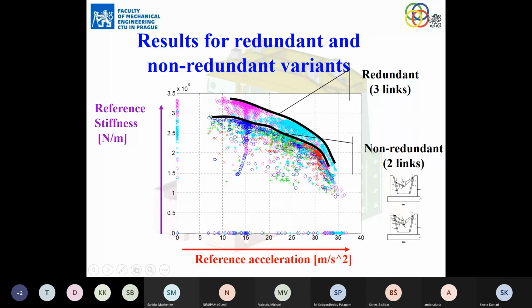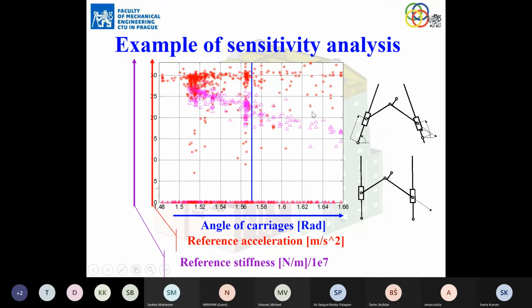Before that was one decision. One decision was whether we have redundant actuation with 3 actuators for 2 degrees of freedom, or just 2 actuators for 2 degrees of freedom. It was decided that the improvement is only about 10–20%, and it's risky for new technology. On the other side, we realized that if I go from the parallel sliders to skew sliders, we can gain again 20% more.